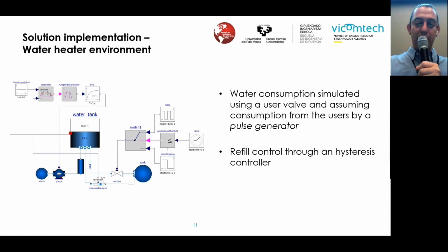The resistance will heat the water and keep it around 60 degrees, which is typical for hot water accumulators. And then the power demand estimated is the power to heat. Now the pump is so small compared to the power used to heat the water that it can be neglected in this case. So that's what they have done.